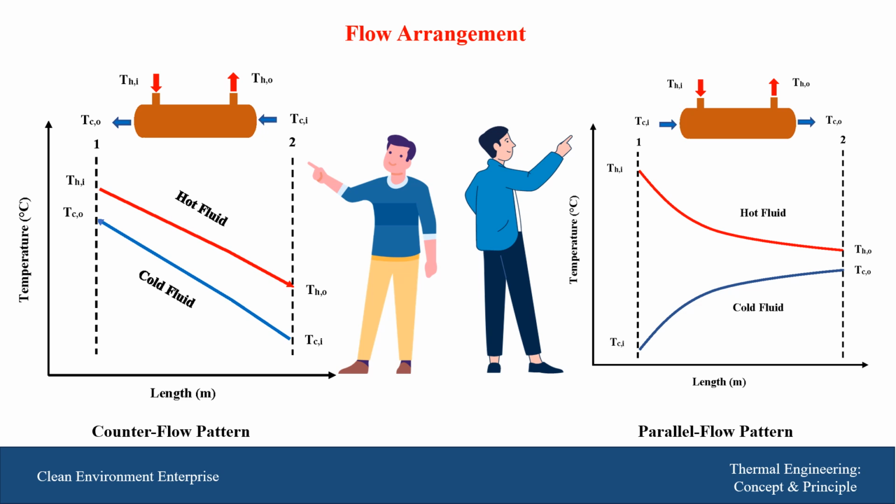So if we talk about the counter flow heat exchanger, if we have a look at the blue line, which represents the cold fluid, it enters at T sub Ci and leaves at T sub Co. And when we have a look at the exit temperature, there is a possibility for it to be higher than the exit temperature of the hot fluid.